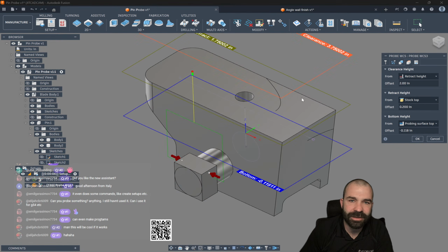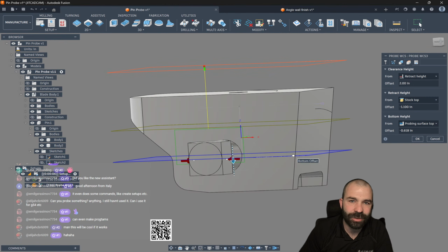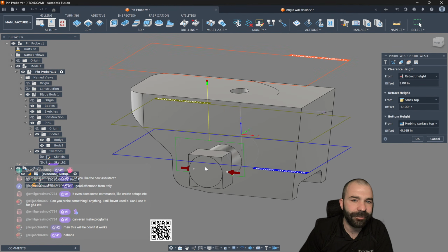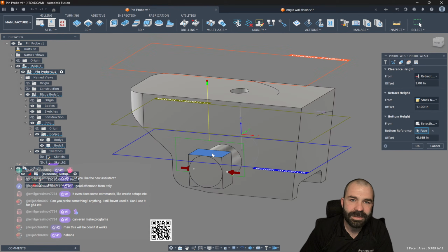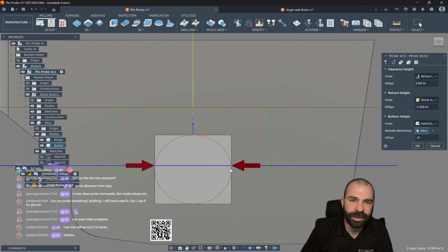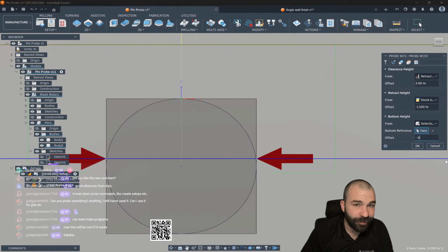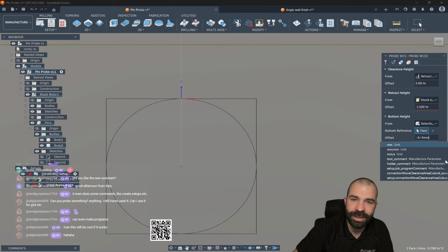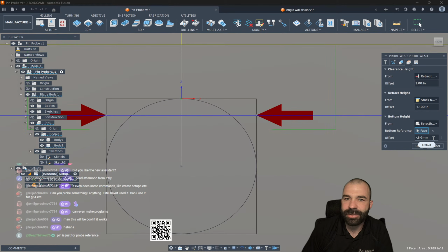Now, if you're going to live dangerous here, guys, I understand that a lot of you like to. We could always bring that top height down. Could also get down closer to the center line of that pin. And if you know the dimensions of the pin, again, as you guys may or may not know here, you could actually say selected height top, and then you could subtract that by whatever that radius is. I'm going to make a guess that it's 0.5, and you might need to go even further because we don't want to be hitting anywhere that's not technically tangent. So for all of you out there, you could actually add 3 millimeters to this, or in my case, we don't need to add, we need to subtract the 3 millimeters.